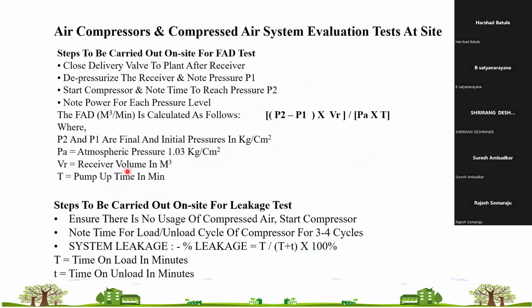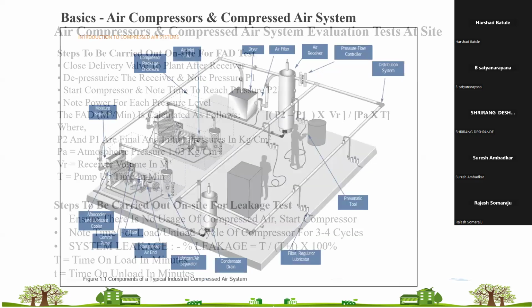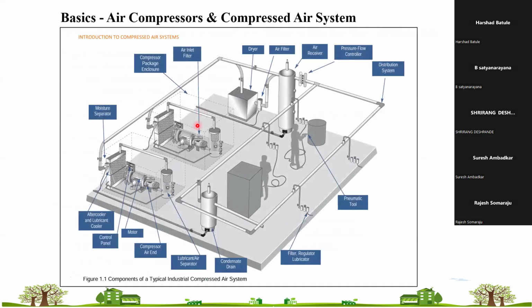So this is your ideal plant. If this is your plant, there is compressor modulation, or usage of compressors. You have a 100 CFM compressor and then a 200 CFM compressor. The situation is that both compressors run, and your 200 CFM compressor is in load unload cycle, and the 100 CFM compressor is on continuous operation, continuous loading.